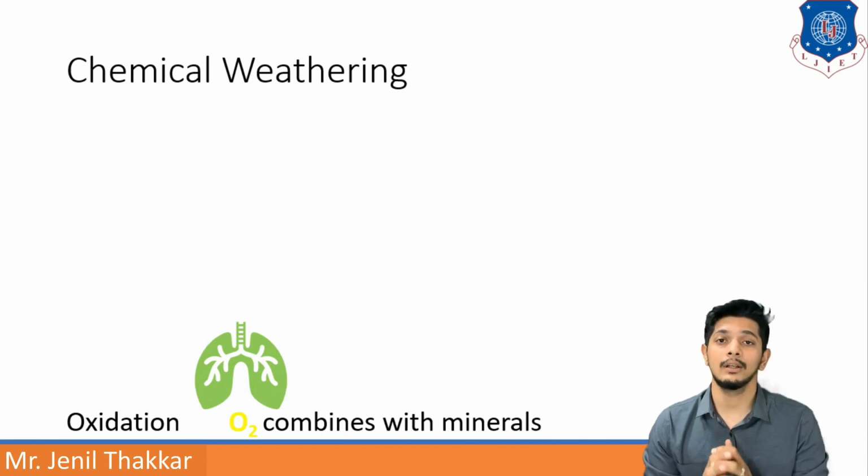Furthermore, in physical weathering, cohesionless soils are generated like gravels and sand. We have seen the examples of that. In chemical weathering, the cohesive type of soil is generated like silt and clay. So, you must know the basic difference between these two processes.